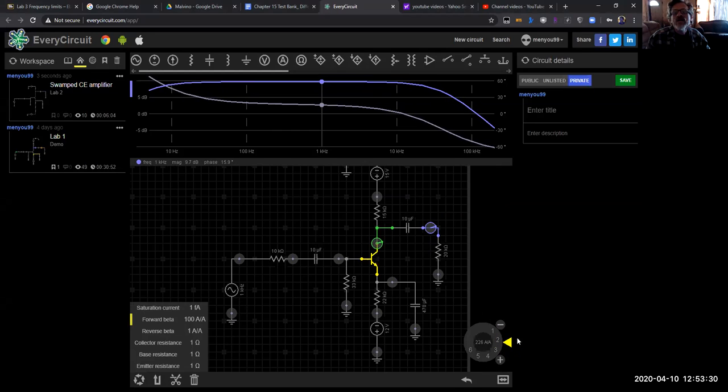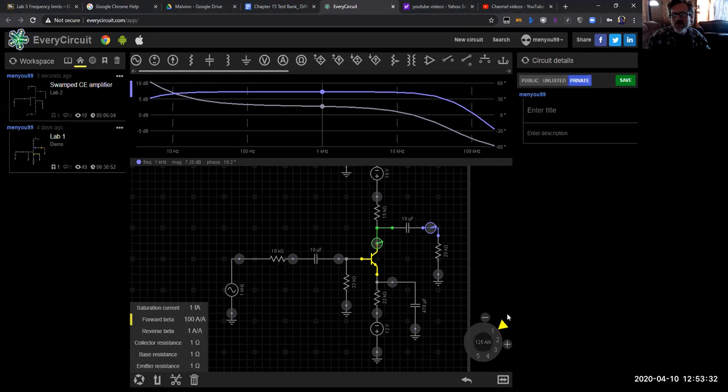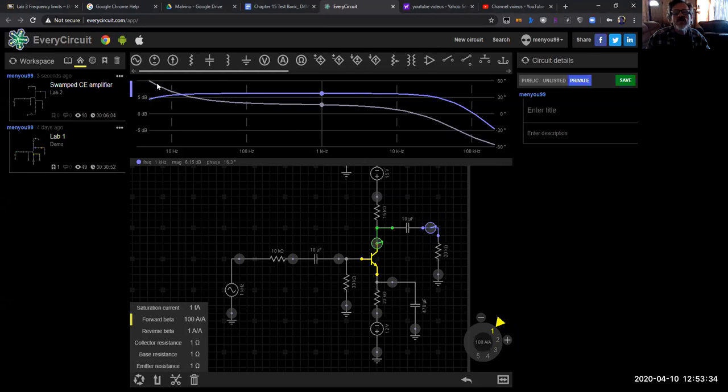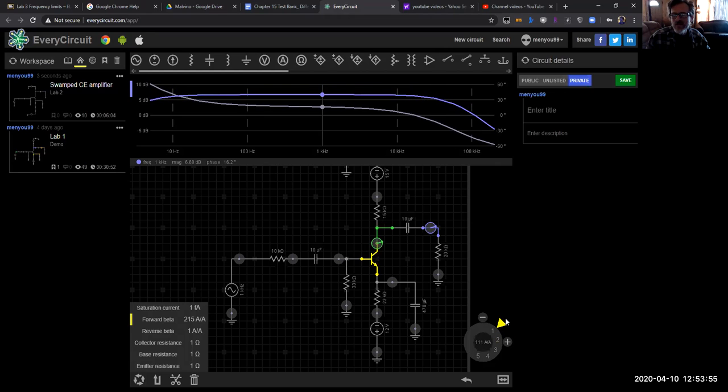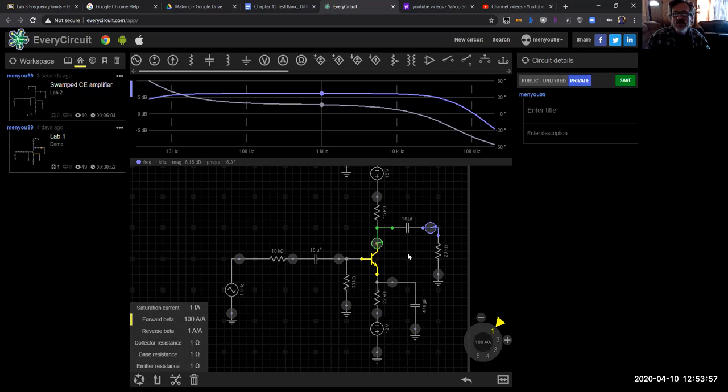What do you think? There's my Bode plot of the output, right? So if I start at 100, we can see with the Bode plot what the overall response is. And I have a 40 millivolt signal going in, just like the directions say. But you can see as we increase that, our response changes, and we start changing our phase. So that will help you answer that question. And then if we change these values in here, let me take a peek.